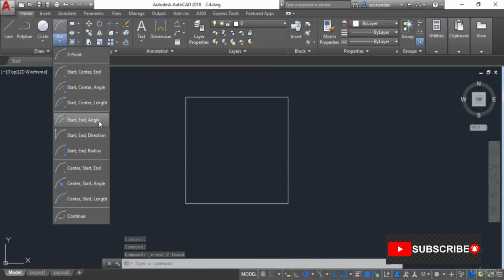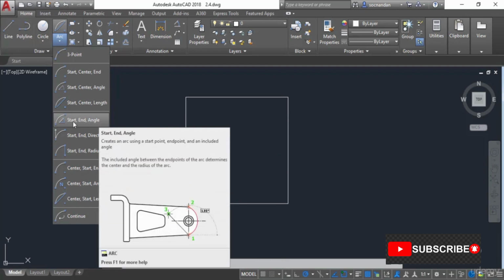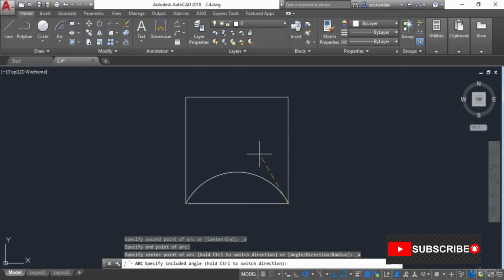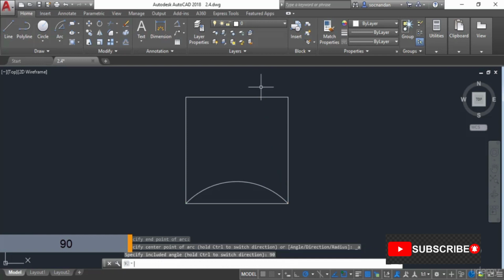Now we have these options in which we generally need an angle. Here also we have the start point, end point, and then angle. So let's click on the start point, then the end point, not the midpoint. Here I'm clicking for my end point, and now we need to specify the angle. This will be the included angle of the arc. Here also you can click anywhere in the drawing area to specify the angle, or you can also type the angle value. So I'll simply type the angle value, which is 90 in this case, and press enter.